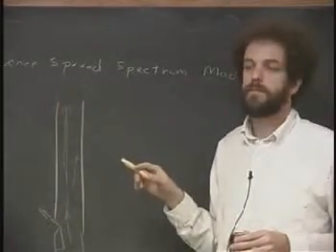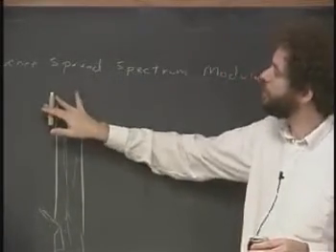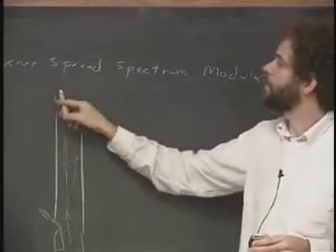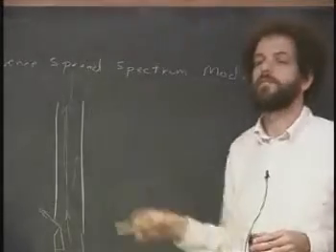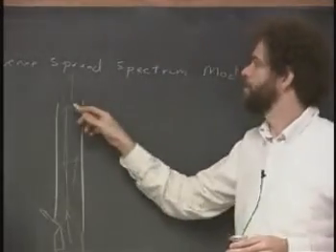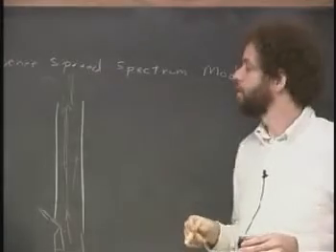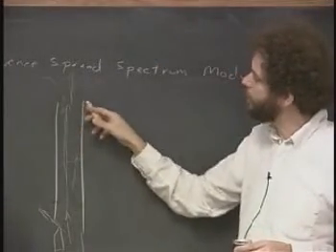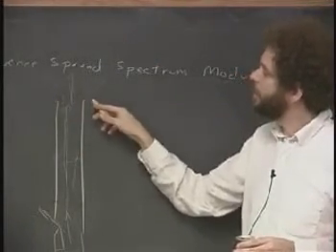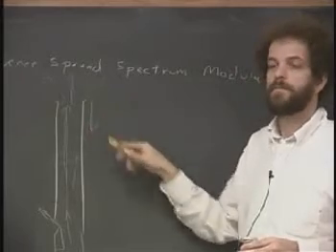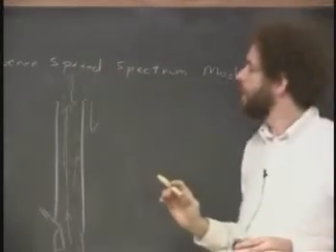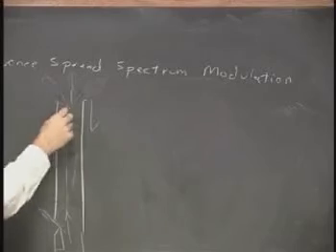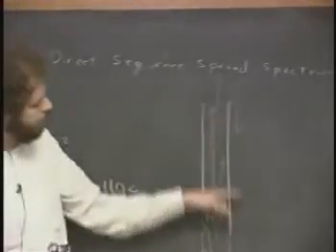They finally get to the end, okay? And when they get to the end, if the tube looks just like this, they will pop out, and all of a sudden they go out into the big wide world where the pressure is the same and the velocity is 0. Or actually it's not quite 0, but they can go out and have speed when they go out. What happens when the wave goes out here and there's nothing at all here is that a new wave is created that bounces back. It's what's called an open circuit. Goes out and then all of a sudden, pop, there's nothing there. And a new wave begins to propagate down that is the negative of this wave here. And that propagates until it reaches the lip here.